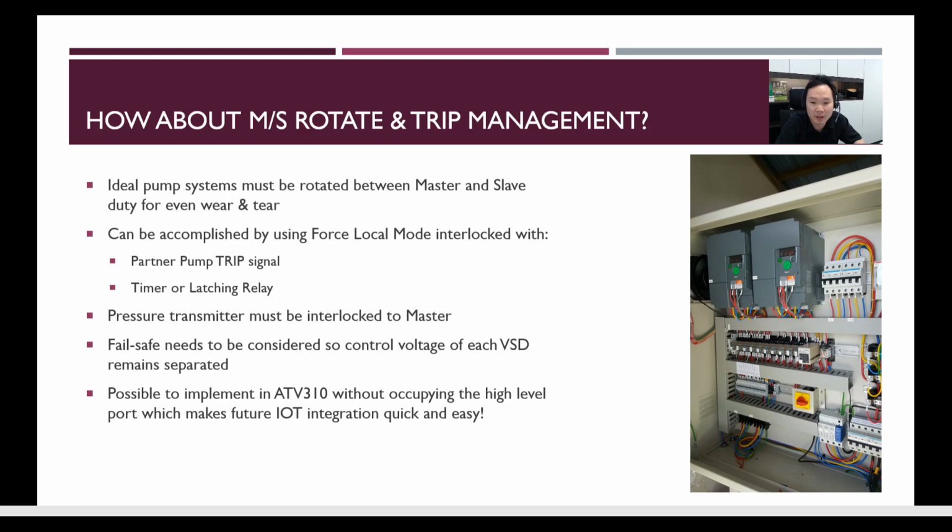Okay, and everything that I have spoken about so far can be implemented without occupying the high level port, our Modbus RS485, which means that in future if you want to hook up the drive into a BMS or IoT or something like that, the port is still free. You can still use the port.